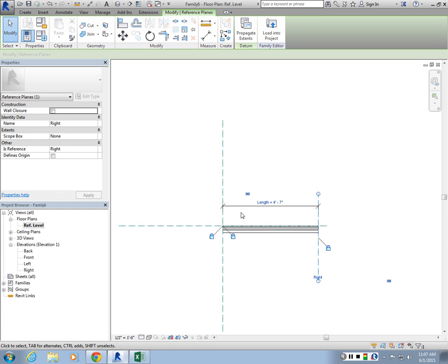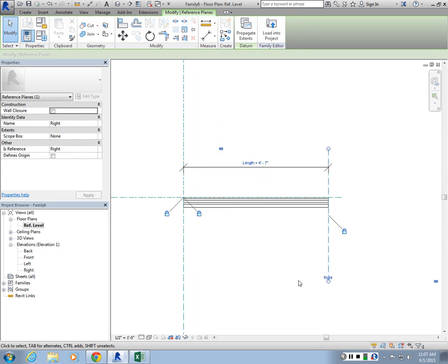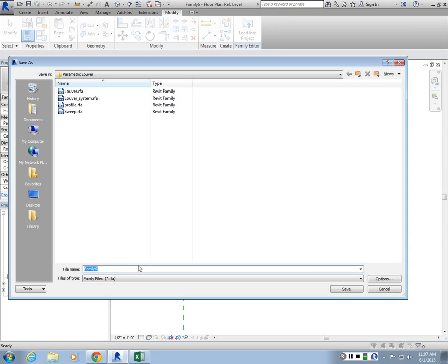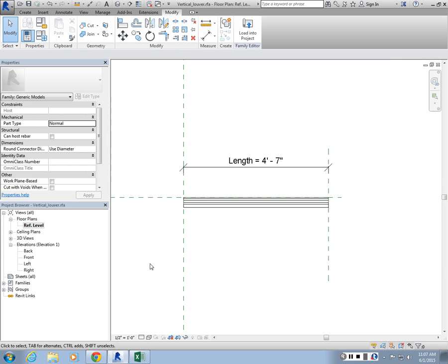But you can also skip those steps, basically, and start with the third step, and then built in one for the vertical. And then use this guy. Let's save this one as vertical louver. Open up a new curtain wall panel and draw a vertical line this time. Okay? And make a horizontal array.